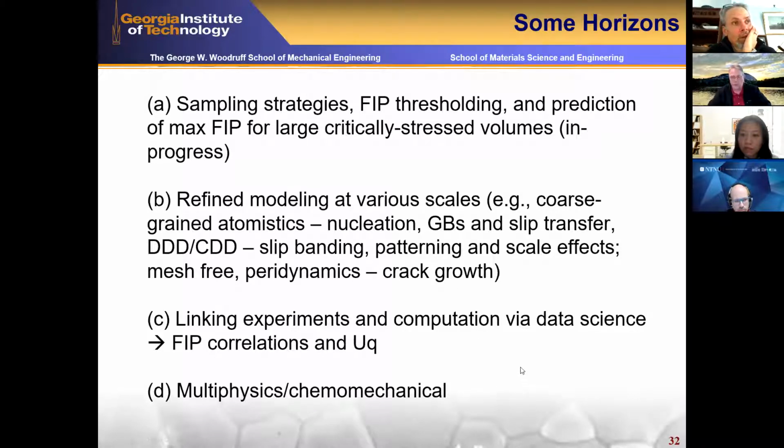We're doing some work now on multi-physics, chemomechanical effects that sort of highlight the desirable aspects of microstructure simulations. When you do fracture mechanics with chemomechanical effects, consider a mechanical process zone and a chemical process zone. And it's a little unwieldy to rectify those, but when you're doing the physics based on direct computation of microstructures with the transport and the mechanical effects coupled, it's very clear, right?